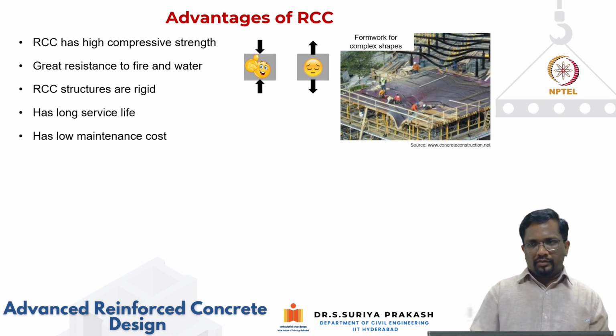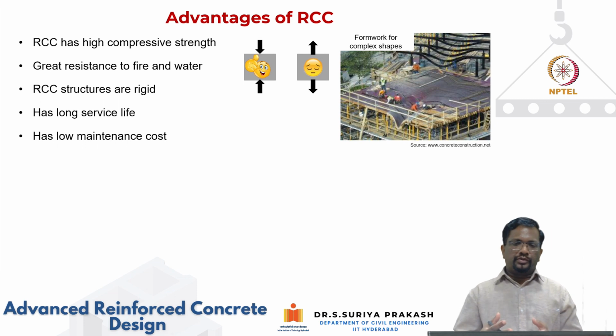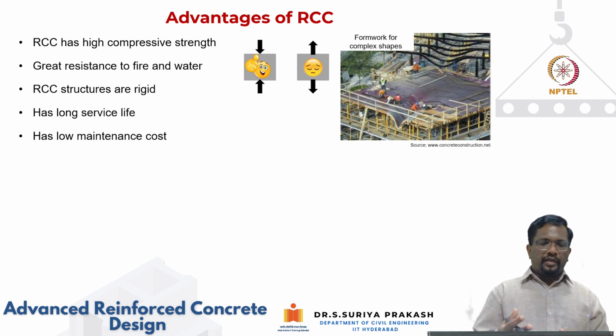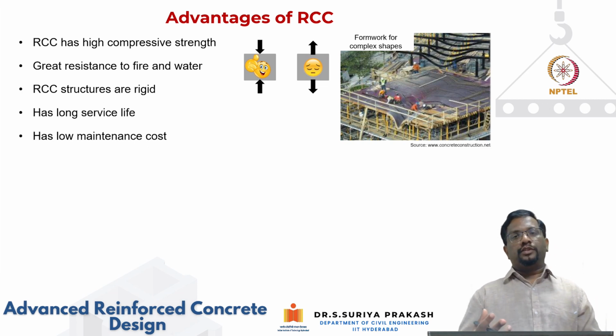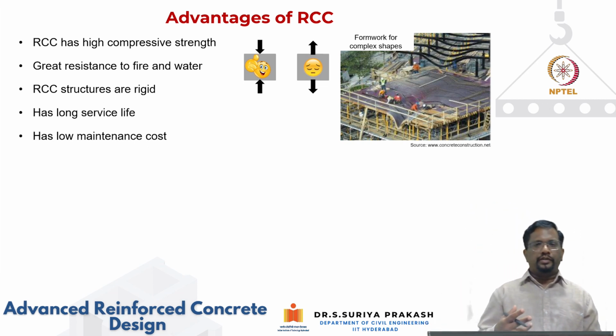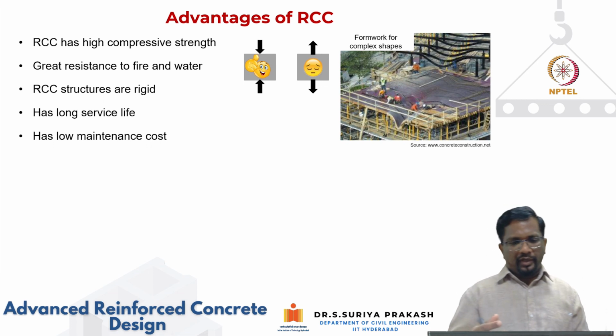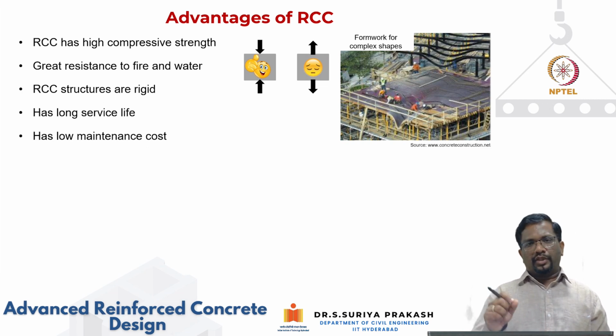Right. So far, we have discussed the history of RC and various structural systems. Now, let's look briefly at the advantages of reinforced concrete. As I've explained, concrete as a material has a very high compressive strength, and it has excellent resistance to fire and water. Of course, with water, we have to be careful. We have to make sure that the concrete is not permeable. Also, for the design load, if it is a water retaining structure, you have to make sure that you design it for a specific crack width or crack free concrete.